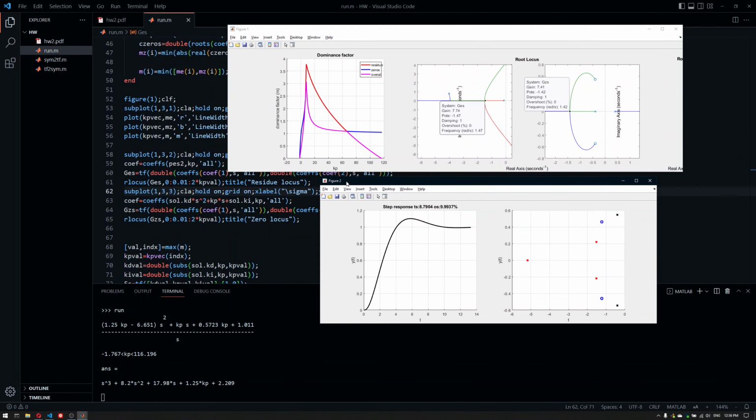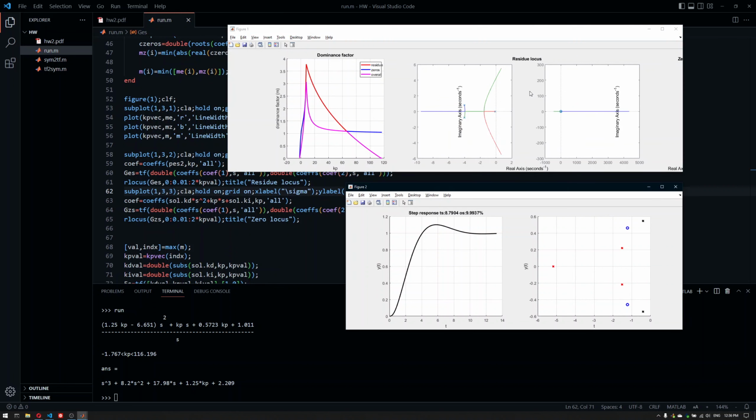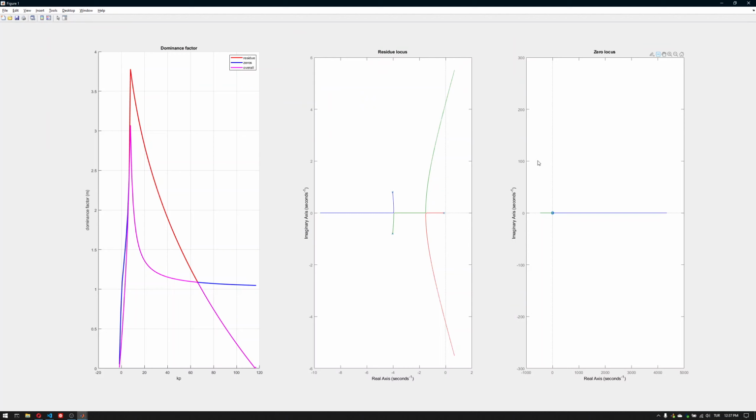So basically, we cannot choose it just based on one of the plots here. The reason is that when we move, for example, the zeros far to the left, we are messing up the poles. And when we move the poles, we are messing up the zeros. So they should be maximally away together as far as possible. That kind of messes up the whole process here. And you can see that in this interval, we already have an issue about the zeros here.